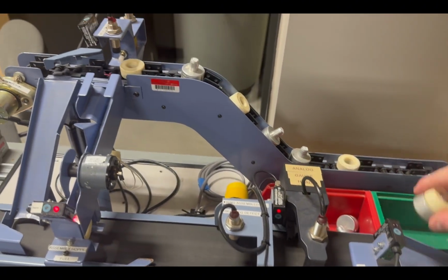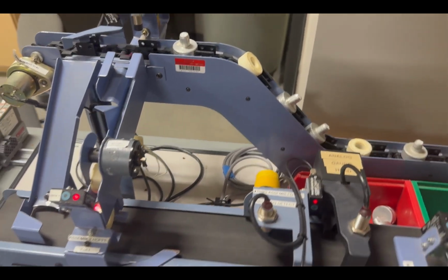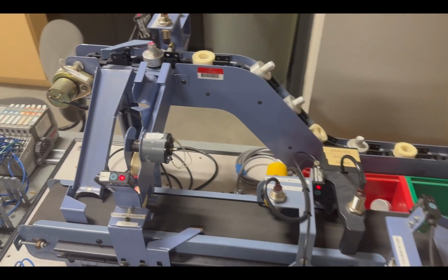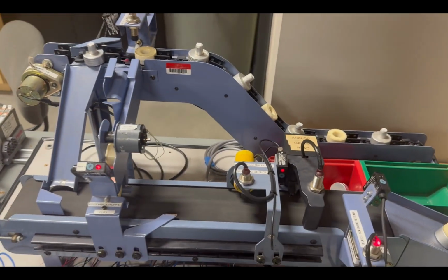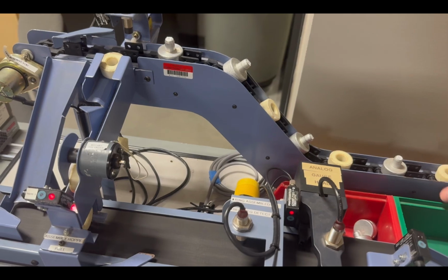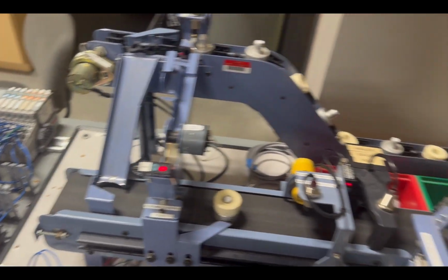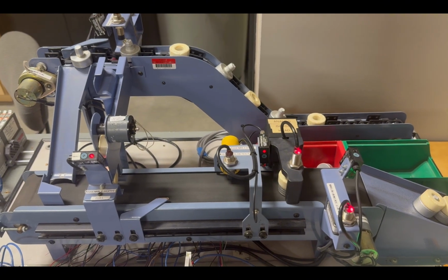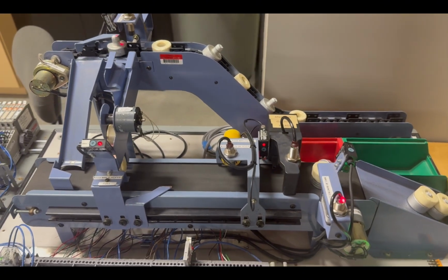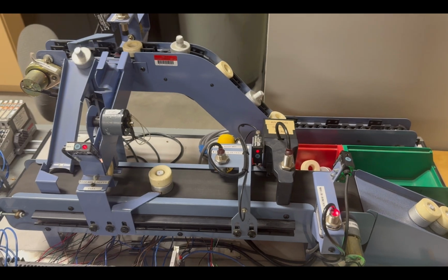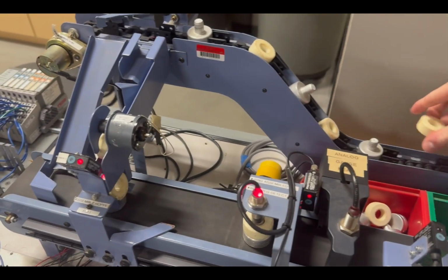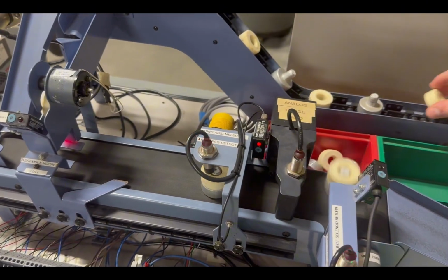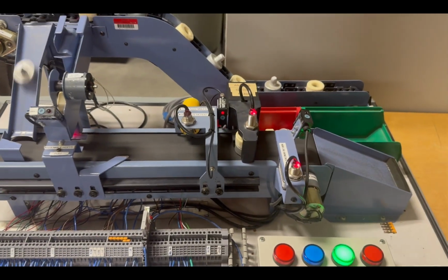And there I am loading up the chain conveyor again with the plastic rings and metal pegs. The sort solenoid sometimes does not get them all the way down the chute, which was a problem I had. That one will get rejected by the reject solenoid. Analog also gets rejected there.